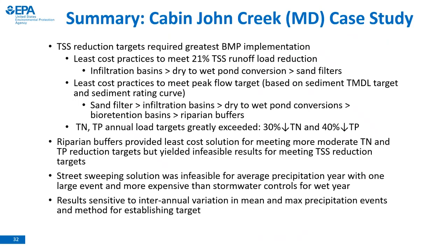Not surprisingly, the total suspended solids reduction targets require the greatest BMP implementation to meet the 21% load reduction. Infiltration basins followed by dry to wet pond conversions followed by sand filters. Maryland Department of Environment actually had a slightly different way of setting and meeting sediment TMDLs based on peak flow targets.